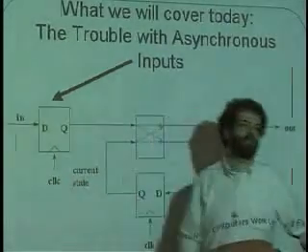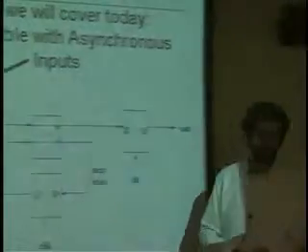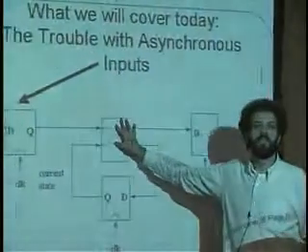This clock here is sitting there running at some frequency all on its own, and the input can come at any time. Now, I've solved it a little bit. Here's what I've made better than it used to be. I've at least simplified the problem. I've made what is wrong with this thing kind of stick out like a sore thumb now, because it's not hidden behind a layer of logic on the input here.